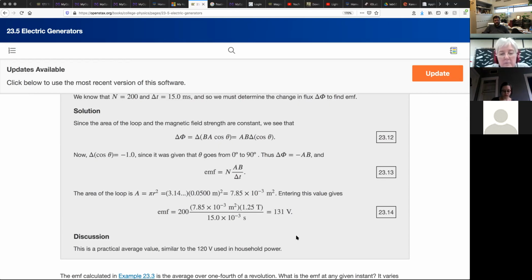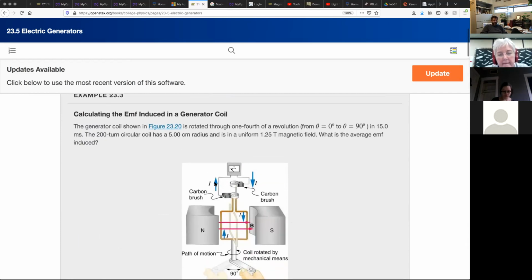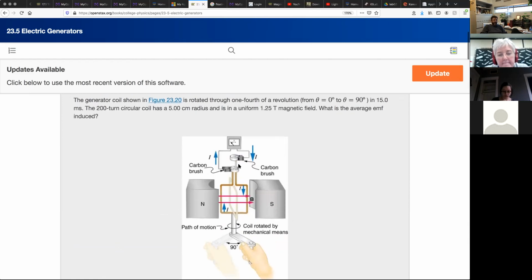I have a question. Yes. Is this the same type of thing? You see those radios that you crank? Yes, exactly. That's exactly what they do with those crank radios. They connect it to a generator like this, and they create an AC current, and the AC current runs the radio. They actually may do it with a DC current, but all they do to do that is they put a commutator and they have one commutator and 2 halves of a loop, and then they get a DC current. So they may deal with a DC current, but it's still the same concept in its basic form.